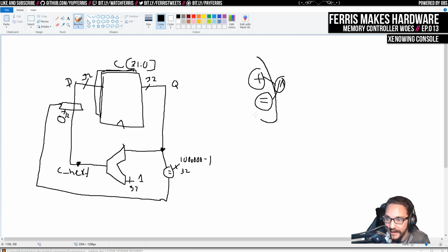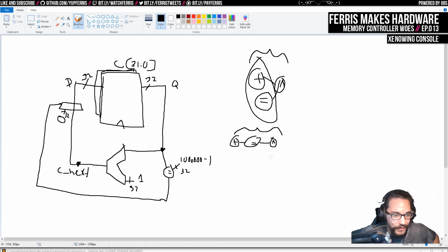So these could actually happen in parallel in the hardware. Whereas if we did the add and the compare, then we'd have this kind of chain with the dependencies, the add, the equality, and the mux. And so clearly this period of time can be shorter than this period of time. That's kind of the important thing.